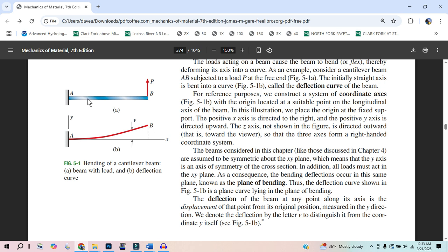So just always internal loads. You should use this, take this little segment, put it up here, do a little free body diagram. Your loads on this cut, the shear that causes it to rotate counterclockwise is the negative direction. When we do the cut, the shear is always going to be wanting to rotate it clockwise, which seems counterintuitive. I'll make a video on that.